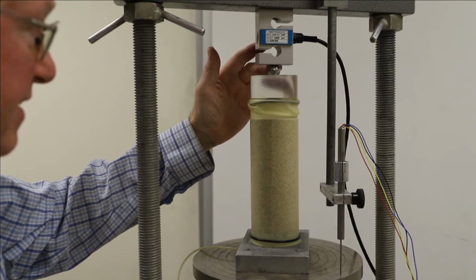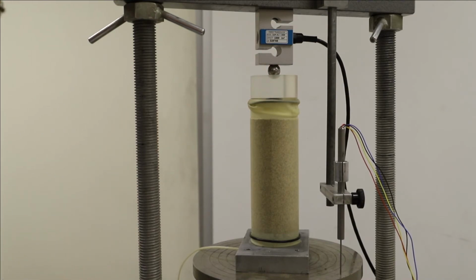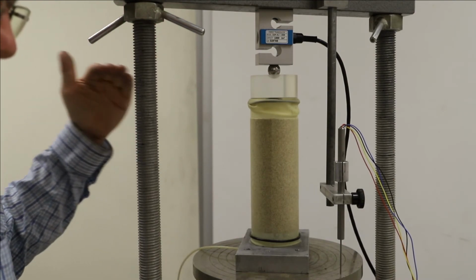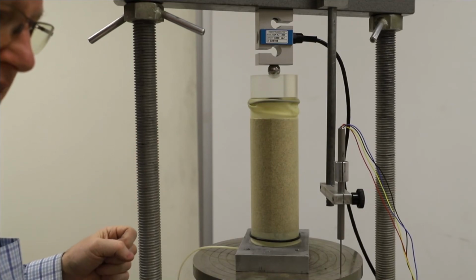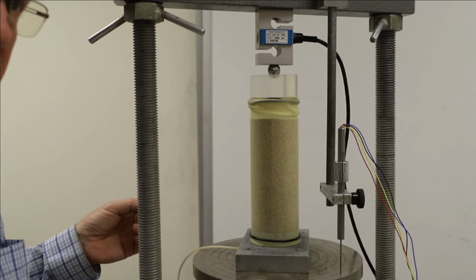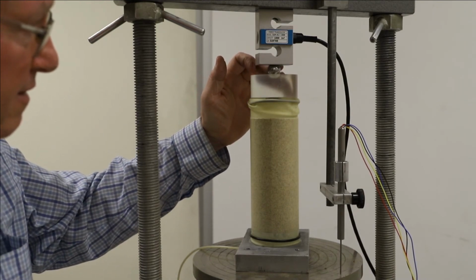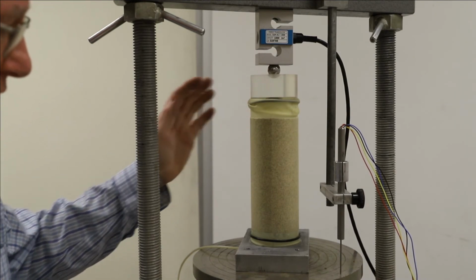Again, there still is not contact, so our early data readings are going to be without significant load. But then when we get contact and you see a departure in load from the initial flat value, that signifies the beginning of the test. That's the LVDT reading from which you calculate zero strain. And we have contact, we're rolling.